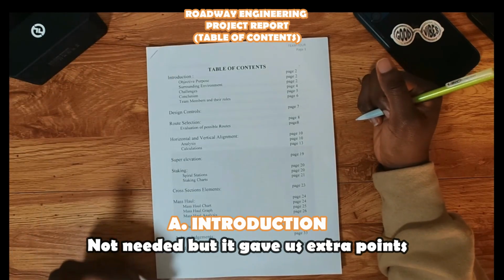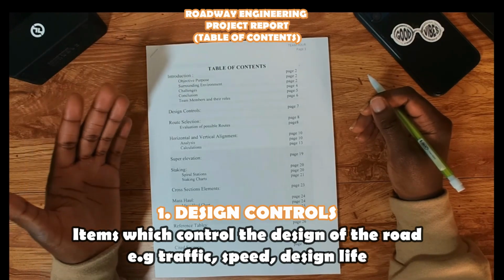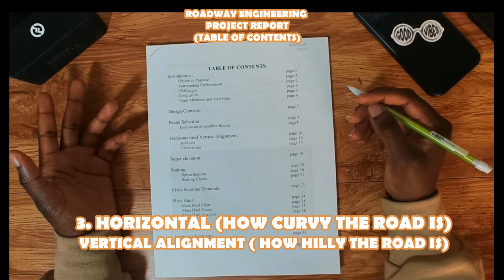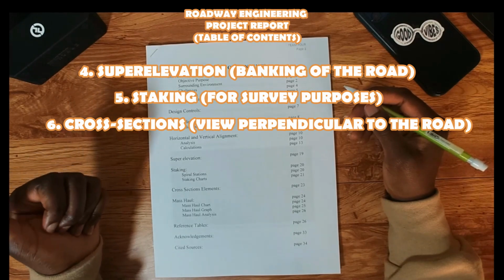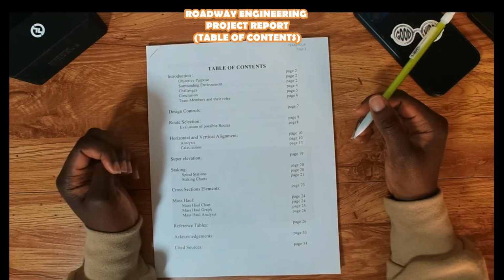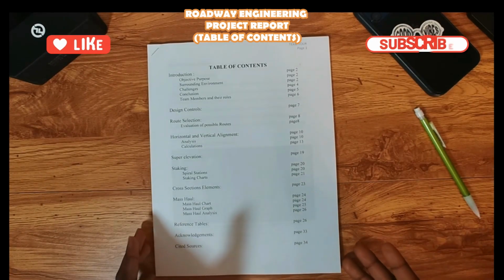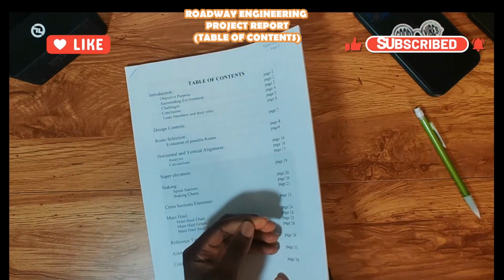Everything after that is basically the design of the roadway. The design controls came first, and then we went ahead to select what route we're going to use. Once we selected the route, we went ahead to design the horizontal and the vertical alignment. Next, we had to do super elevation, staking, cross sections, and the mass haul diagrams. So this is all step by step what we had to do for this project. It also came with project plans, which was quite a thick document. But this is what the table of contents looked like, and it was roughly about 34 pages, and this is how thick the document was.